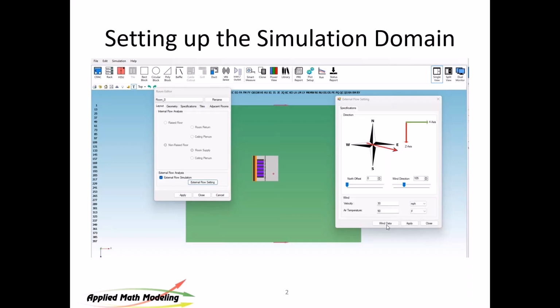Or sometimes the customer will tell you what prevailing wind they want you to worry about, because they have a history with the site. In other cases, you want to pick a particular wind because of the way you're building and the way your equipment's lined up, you need to worry about a particular wind direction. And if that is the case, then you simply pick the one you think is the worst case condition and run under those modes, and understand the probability that that kind of wind would blow and what the impact would be.